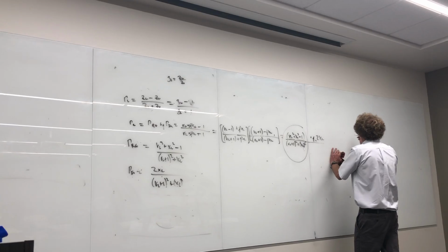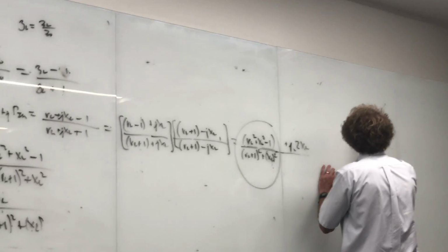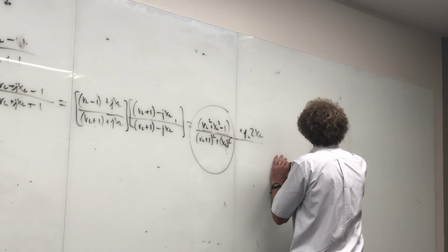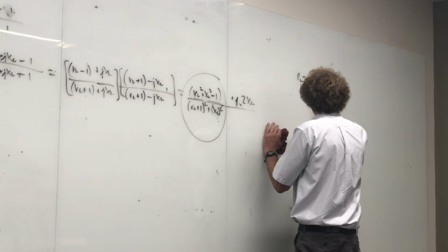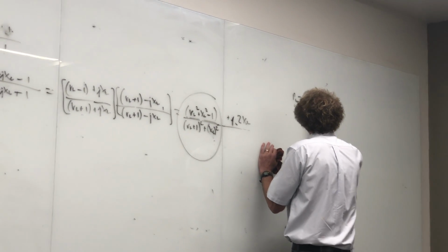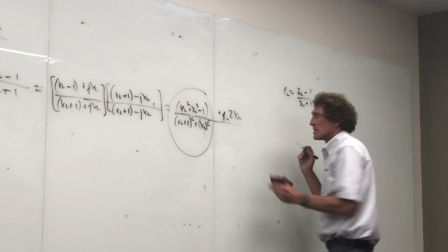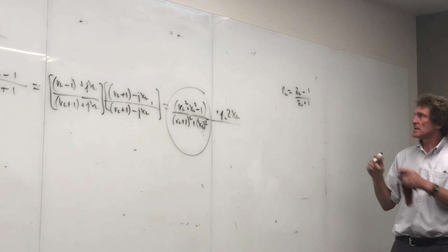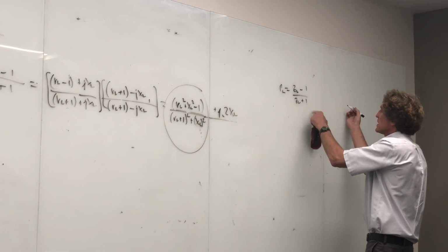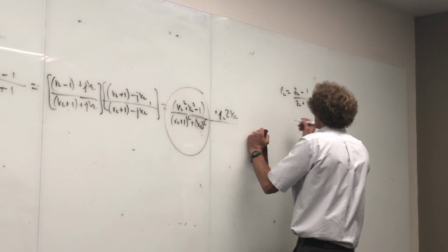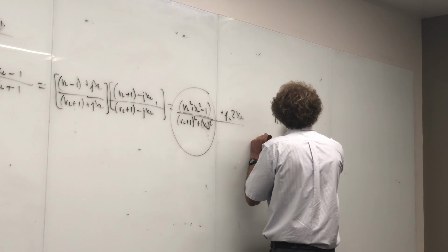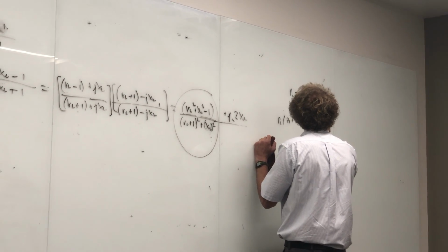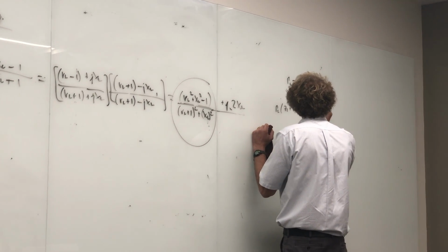He says that when I have reflection coefficient equal to z_L minus 1 over z_L plus 1, right? But I can just as well get z_L from that, and I can say, if I do z_L, just watch this, I can take gamma_L times z_L plus 1 is equal to z_L minus 1.